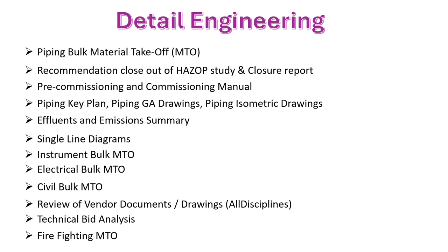Okay. Then we have to procure the firefighting MTO material, whatever material or quantities are required for the execution of the firefighting network. That may be peripheral or inside the plant building. Okay, that includes the sensors or fire extinguishers, then filters for breathing air, SCBA suits, and all these things are to be part of detail engineering. Okay, and based on that, we proceed to the pre-commissioning activities.